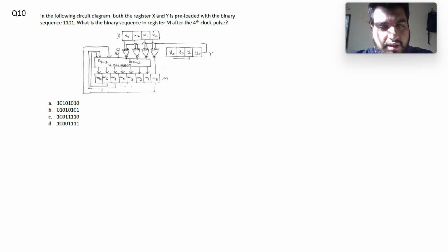So we have this register and we have this shift register here. From the lectures there is this difference. The shifting happens here like this, not like this. So that is one key difference here. We have this M where this AND product goes directly to M0, and for the M register, bits M1 to M7 go to the full bit adder as A7 to A1, and these go as B1 to B3, and all the other 4 bits are 0 0 0.